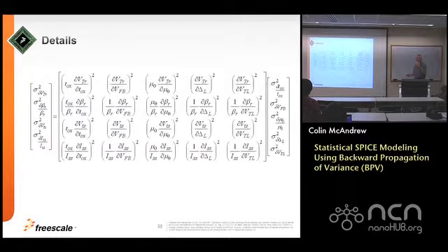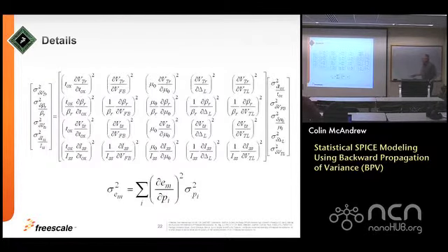This is that set of equations for a MOSFET. So this is the variances in the electrical performances. The subscript R is a reference, which means wide long, and S is short, which is a wide short. You'll notice that the beta here is the gain factor. This is the threshold of the wide long, threshold of the wide short. This is the gain factor, and this is the saturated drain current. And here I've got a relative variation instead of an absolute variation. And then this is that matrix of squared sensitivities, and this is the matrix of the parameters.